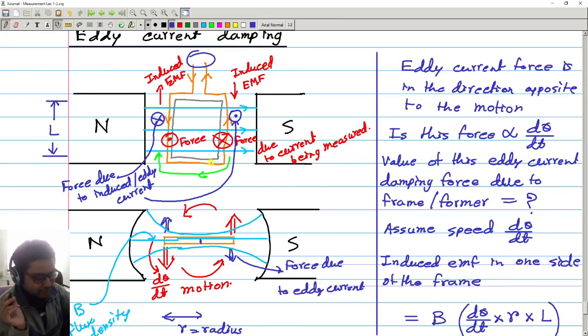Okay, so that sounds reasonable. Sir, even if there is some eddy current, we can always calibrate. If we pass some current, we will get some angle. Then we pass some more current, we get another angle. So we can calibrate the instrument like that, even if some eddy current flows. The first thing is there won't be any eddy current once the pointer settles down.